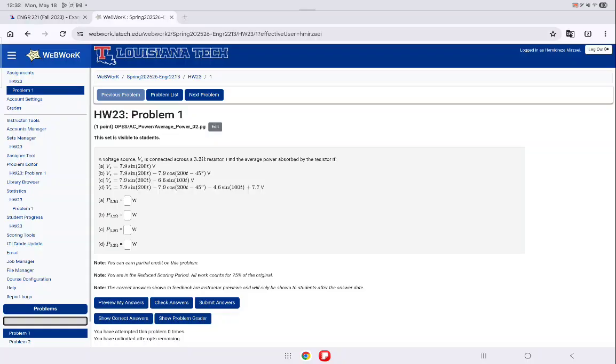Okay, so what about this question? Do you remember the formula for effective value? A square root of 1 over T integral from 0 to T of the signal. So you have the signal. The only thing that you should be careful about is that the T is not the period of the first cosine or the second cosine, it is the period of the whole signal together. Did that make sense? Okay, so it's just tedious work on functions.